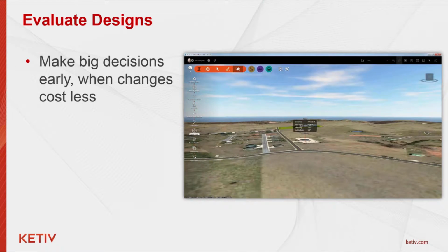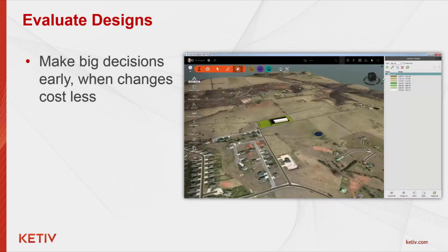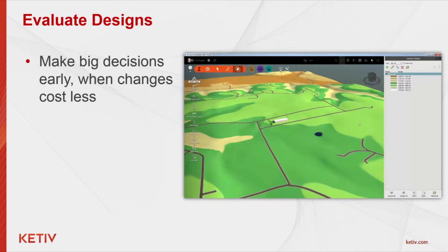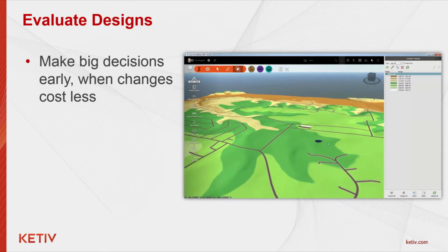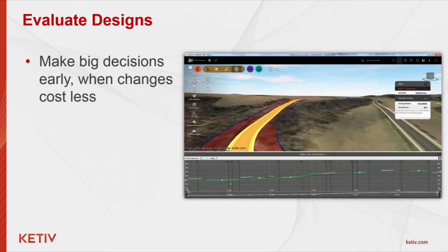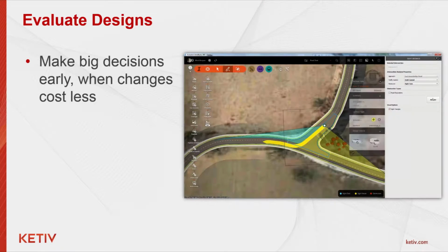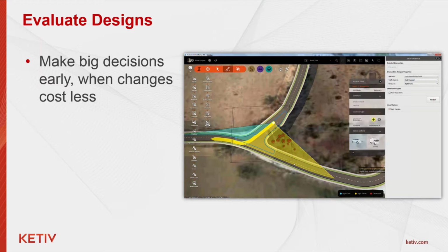Oh, hey, Katie. So with SketchUp, you can import that into InfraWorks 360. You wouldn't be able to just drag and drop it in. You'd actually have to export it to an SKP file to bring that in, and then you could import it in InfraWorks 360 using their data source panel. But you can do that if you want, but there's also the model builder within InfraWorks 360 that will create similar stuff for you right there on the fly in the software. If you want to bring it in, you can.